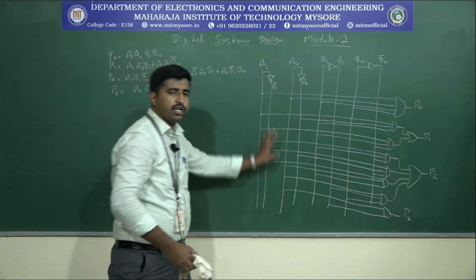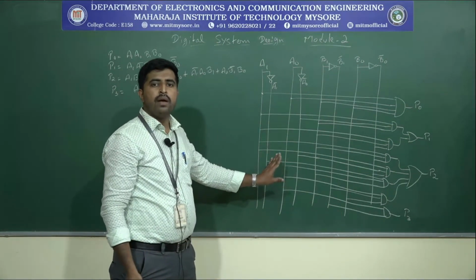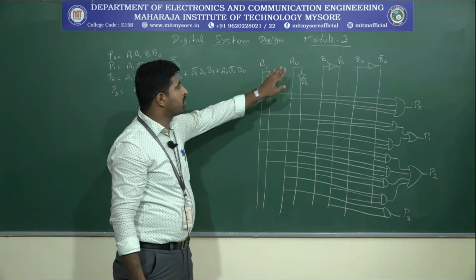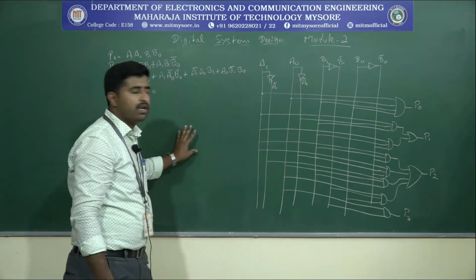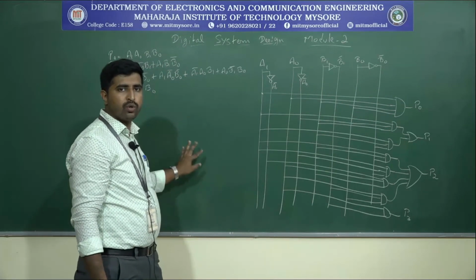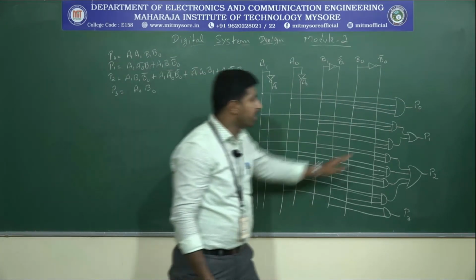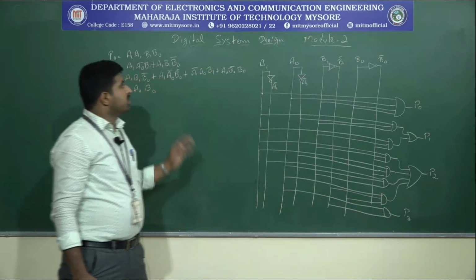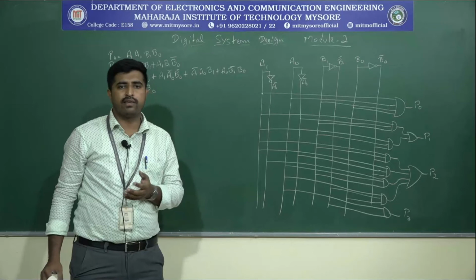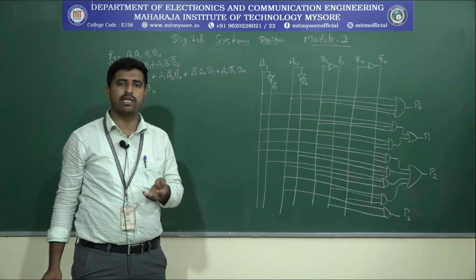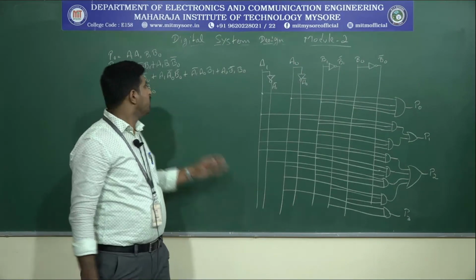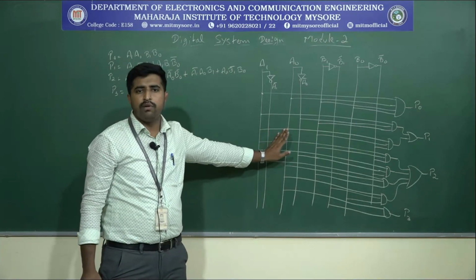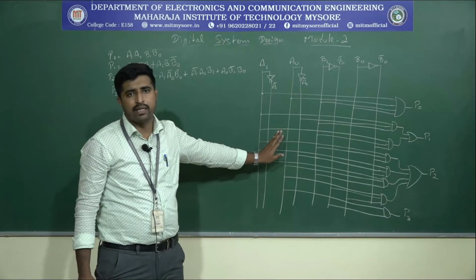So this is the logic circuit that is going to generate the multiplication of the 2 bits. A1 A0, B1 B0. As per the truth table, if you give the inputs 00, 01 like that, we are going to generate the output. So this is how we design a combinational circuit as per our requirements. As per the problem statement given, we have constructed the combinational circuit that is going to multiply the two 2-bit binary numbers.